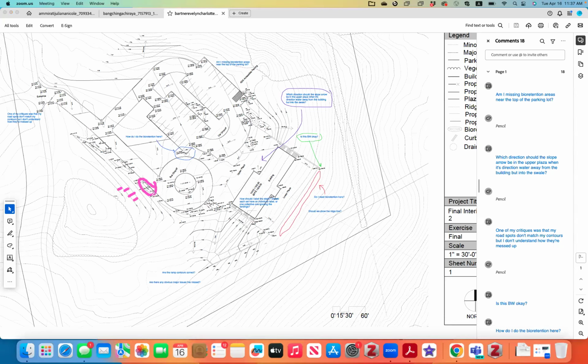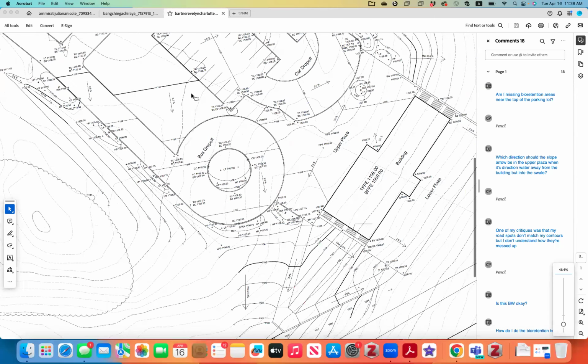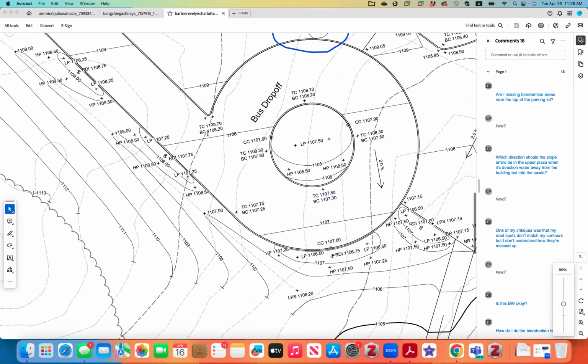These seem very squeezed, and you seem to have more room to move the swale contours to be able to accommodate a more spacious retention area here. Okay, try to measure these, make sure they are 4, and then enlarge those ones.